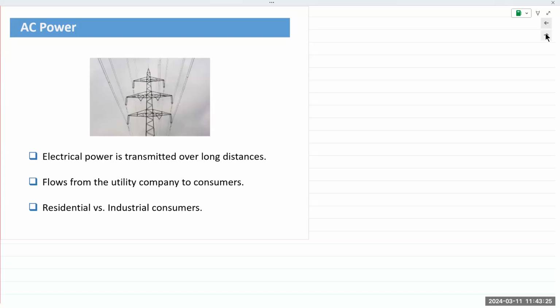But when the length L runs into hundreds of miles, now that overhead cable does have some resistance. And every time electrons pass through an electrical conductor, it encounters that resistance, and a lot of that electrical power is lost as heat. So in a small wire or a small cable that runs like 6 feet or 10 feet or even 100 feet, it is not a big deal. But when it runs for hundreds of miles, it all adds up, and it is a big deal.